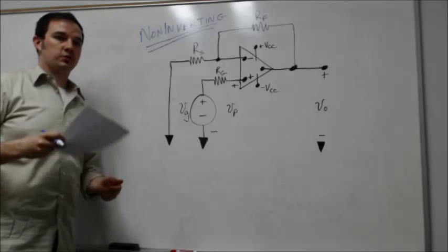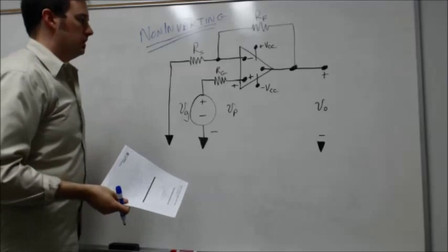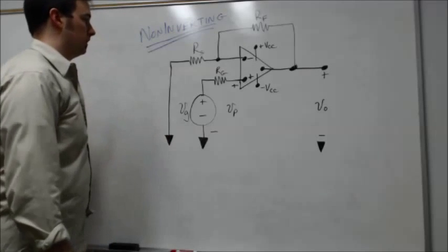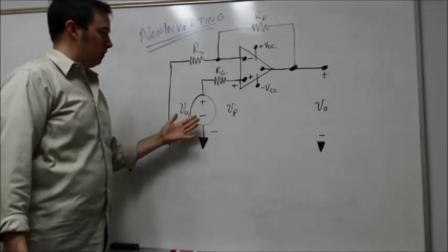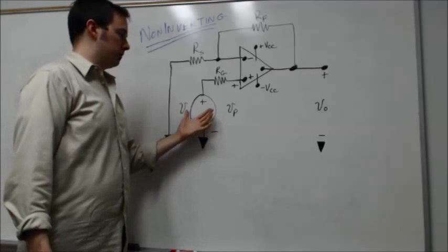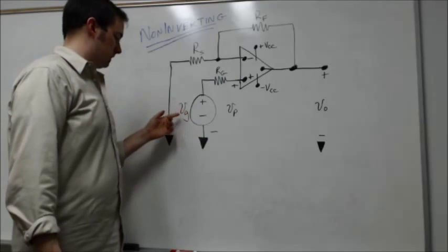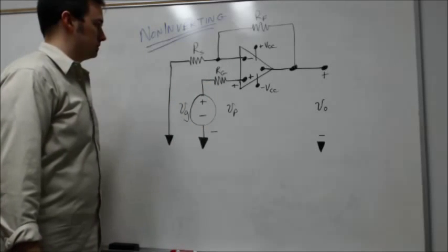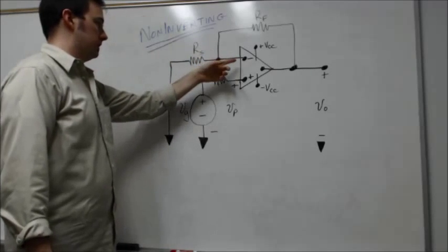And our next amplifier circuit up is the non-inverting amplifier. I figured I'd go with this one next, since we just did an inverting amplifier, we could see what the non-inverting amplifier would look like. All right, so you see here immediately there are some obvious differences. Now with the non-inverting amplifier, you see that my source for my input is going to my non-inverting input. So it's kind of obvious. In this case, we're going to call this one VG, and the resistor that goes in series with it to be RG as well. Then we've added this resistor RS connected to my inverting input here.